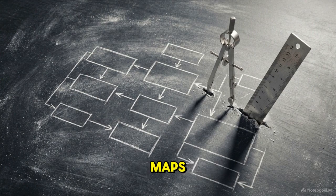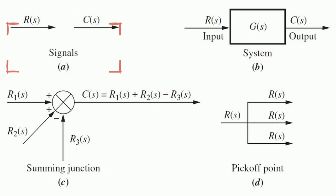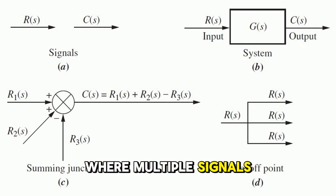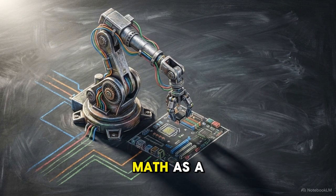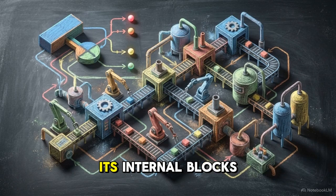This graphical tool maps exactly how signals route through various physical components. This graphic shows the 4 atomic units of these maps: the input and output signals themselves, the transfer function of a specific system block, a summing junction where multiple signals are combined, and a pickoff point distributing an undiminished signal to new pathways. By treating pure math as a physical, spatial topology, you rebuild the structural intuition required to design real controllers. No matter how large a control architecture grows, its internal blocks connect in one of 3 fundamental ways.